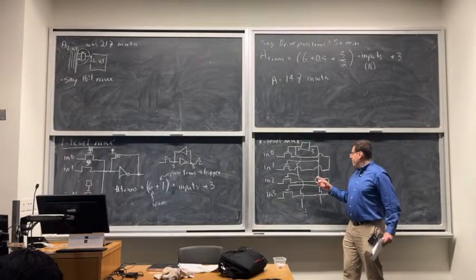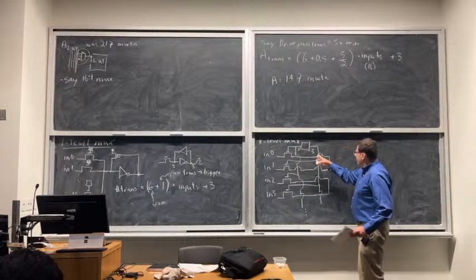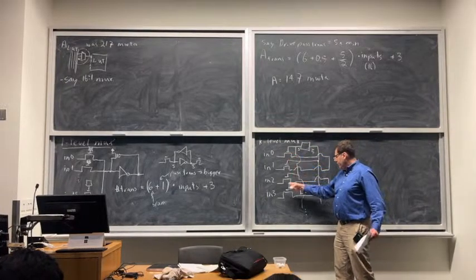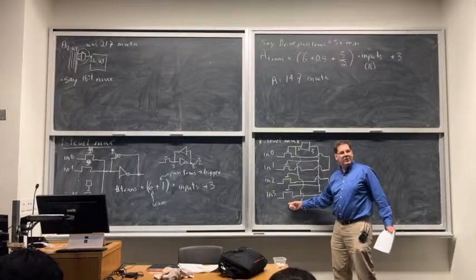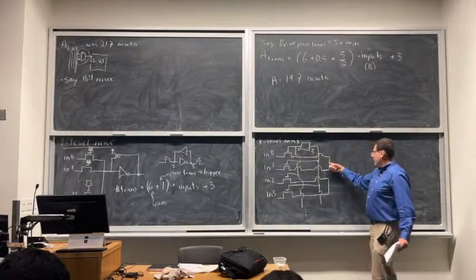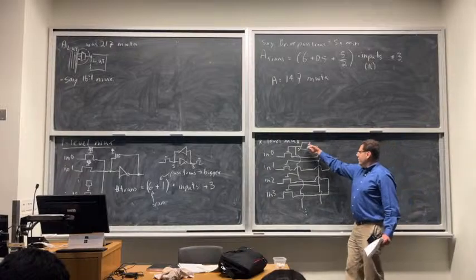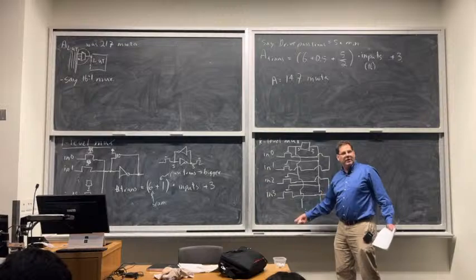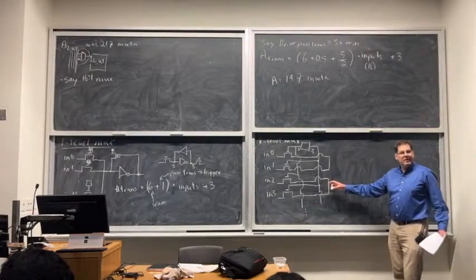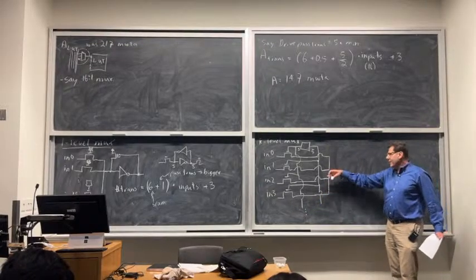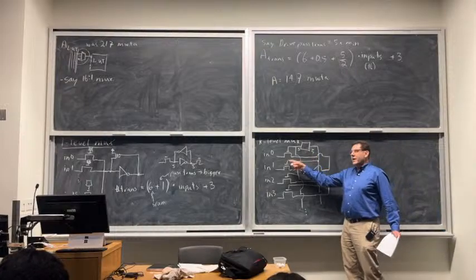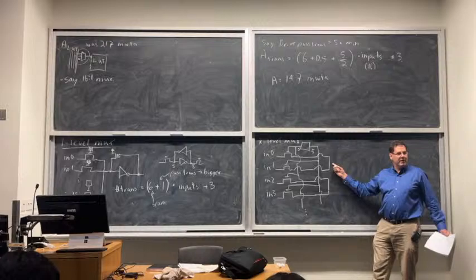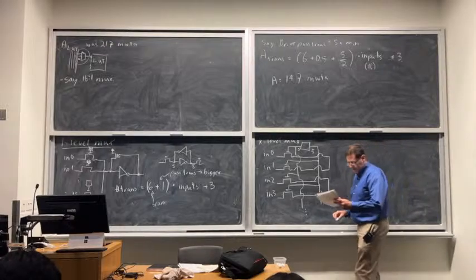And it's basically, if I got a 1 in this one SRAM cell, I select the upper pass transistor here, the upper pass transistor here, the upper pass transistor here, etc. And it goes onto this wire. If there's a 0 here, I select input 1, input 3, input 5, like all the odd ones, and they make it to essentially the output wire. So I'm just wiring together pairs of pass gates, and one SRAM cell says who makes it to the next level of wiring. Okay? Either the evens make it to the next level of wiring or the odds do, but they don't both make it.